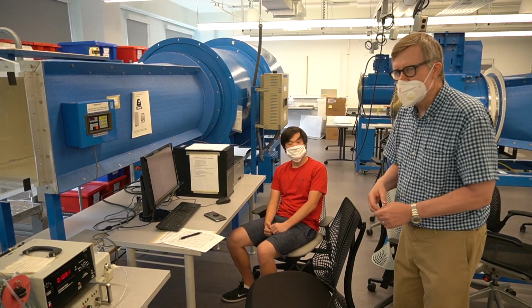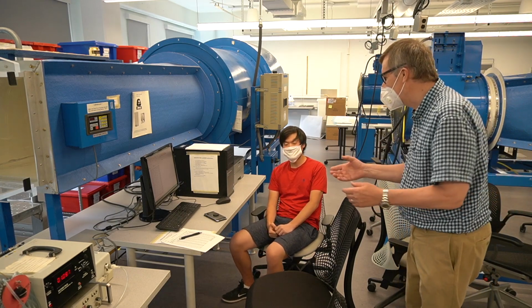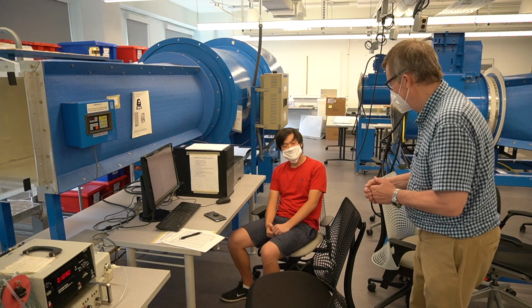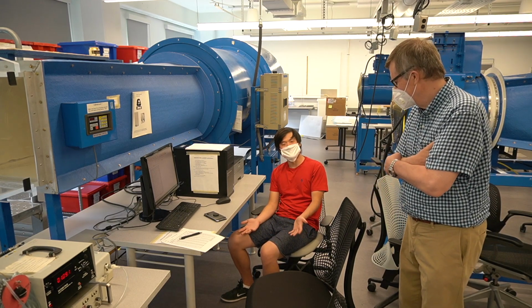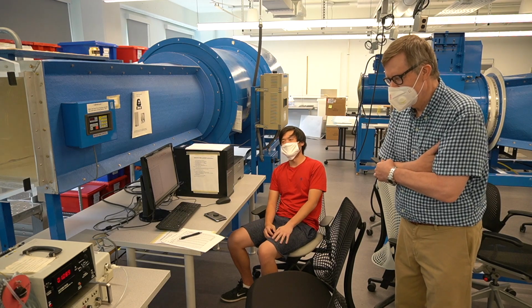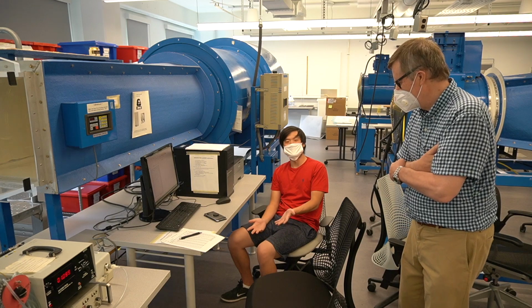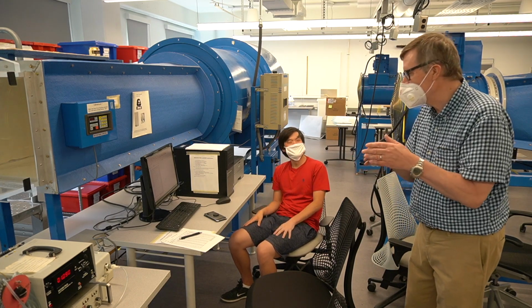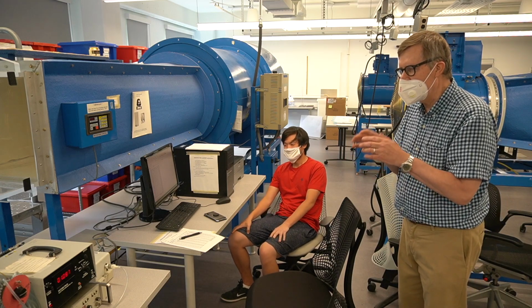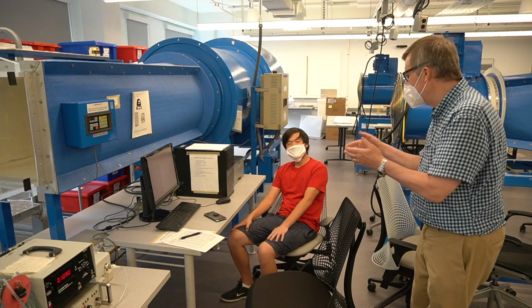Yes, exactly. You ask the right questions, and I'm just a yes man. What's the explanation? Well, since we can't be creating energy in this system, otherwise we'd all be billionaires, then the drag must be on the plate in front of the cylinder. That must be eating most of the drag. Well, the plate's eating a lot of drag, but how come the drag coefficient of the cylinder itself is now negative? What does that mean physically?